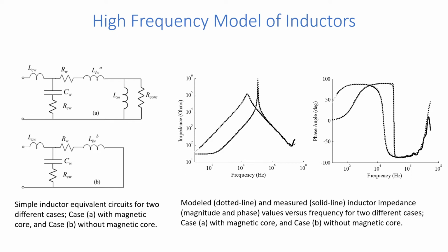In the proposed equivalent circuit, which is built around the conventional magnetic equivalent circuit, we have stray capacitance CW, RCW, and LCW. The winding resistance value, RS, as well as the magnetizing inductance Lm, leakage inductance LLW, and core loss equivalent resistance RCore, can all be calculated from a simple test at the rated current and frequency.